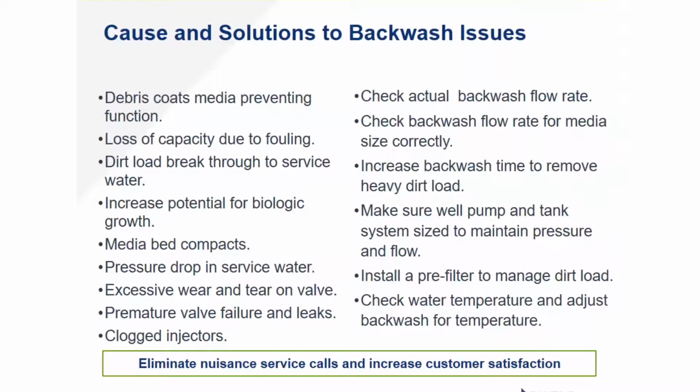What's going on? Check the actual backwash flow rate during the backwash. Make sure you're getting it. If you're not getting what it says on that drain line flow control, you need to do something about that. Maybe that's an excessive length of run. Maybe that's a restrictive fitting or tube, or maybe it's low pressure and flow, low dynamic pressure and flow, where you may be able to change that if you have a VFD pump. Or you may need to increase the size of that storage tank to get you through the backwash. Those sorts of things may have impact. It's probably more likely due to an improperly recharged bladder in tanks.